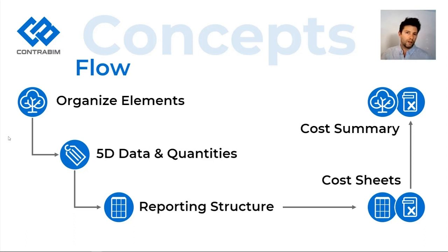And then generally from there, that's a good point to review and condition the data within your model elements to make sure that it's right before you then export it out to another format for sharing, typically into an Excel format where we can build up specific cost sheets and summaries, and everything ultimately with the goal here is to have it flow into a total cost summary that you can then add additional markups on and build a comprehensive estimate with.